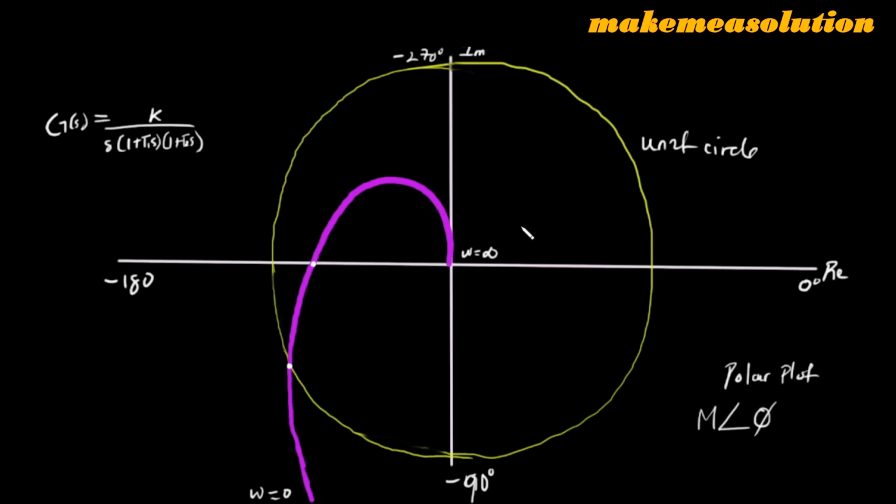Now when we are talking about phase margin and gain margin, we are interested in how our Nyquist plot behaves around one important point called the critical point. Since this is a unit circle, then this point is minus 1, that is (-1, 0). So (-1, 0) is the most important point in control systems. It's the point that demarcates a system between stability and instability or marginal stability.